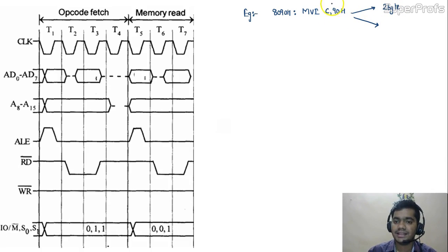It would hold 2 bytes of memory inside the storage, and the machine cycles involved would be fetch and read. So why are we saying that this instruction has a fetch machine cycle and a read machine cycle? Students, it is very important to understand this concept, because in every data transfer instruction it is necessary to understand how many machine cycles it is going to perform. By seeing just the number of bytes, we can understand the minimum machine cycles, but we cannot understand the exact number.